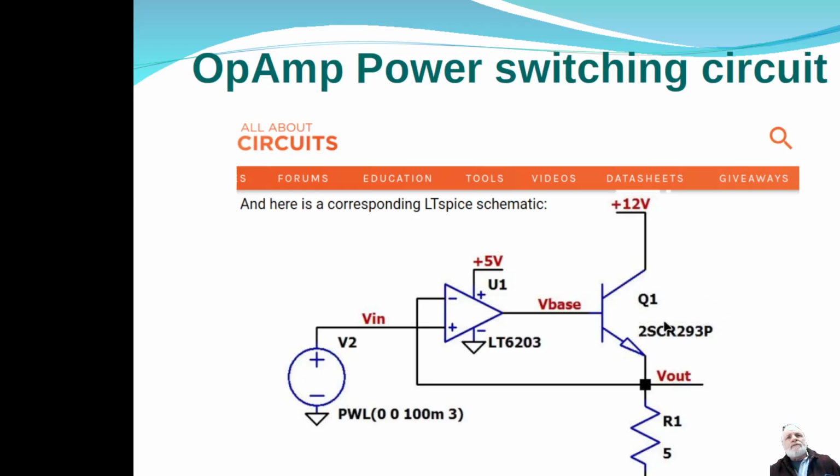And so then depending on which transistor you choose here and your load. In this case, this is a 5 ohm resistor with a 12 volt source. So you're looking at just slightly under 2.4 amperes of current flowing through here.